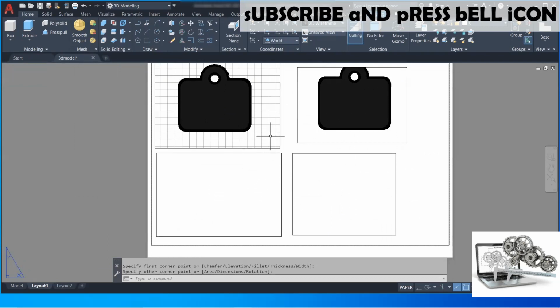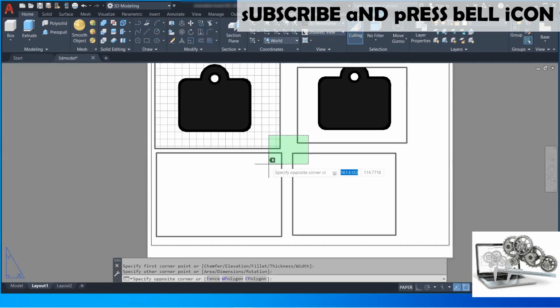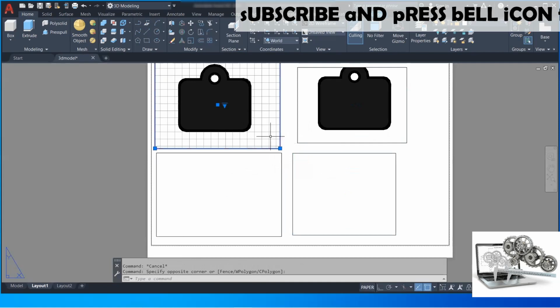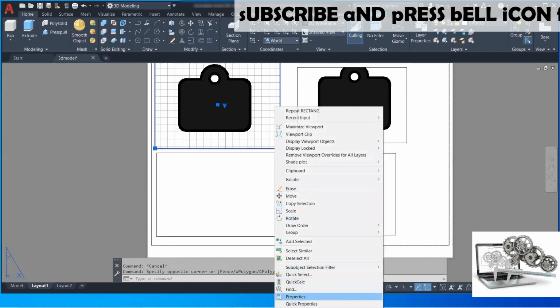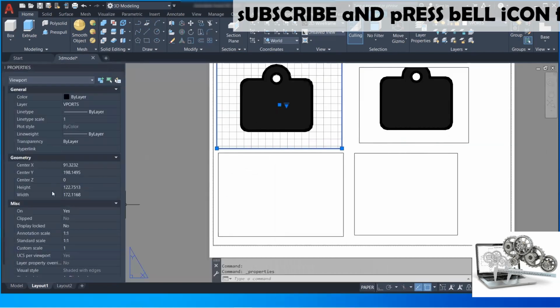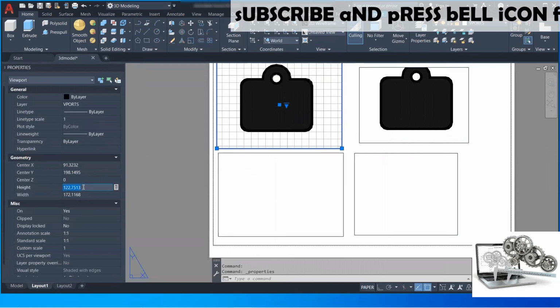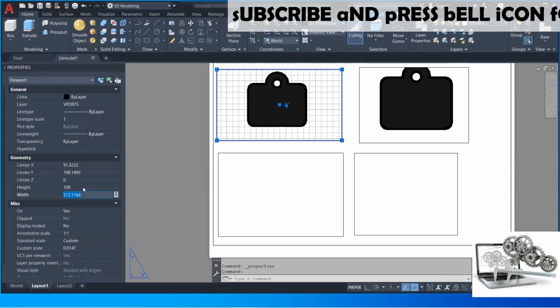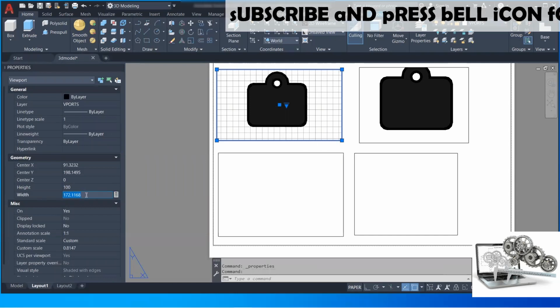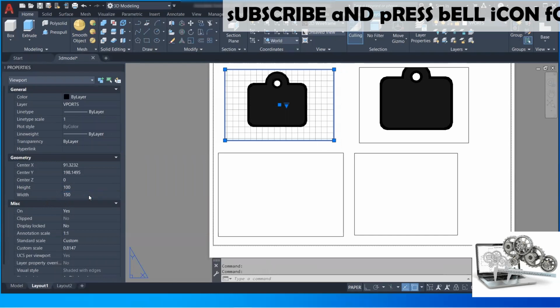After that, select all the viewports or one viewport and go to the properties, and here change the height and the width as per your requirement. In the viewport properties window, the most important things are height, width and the scale factor.